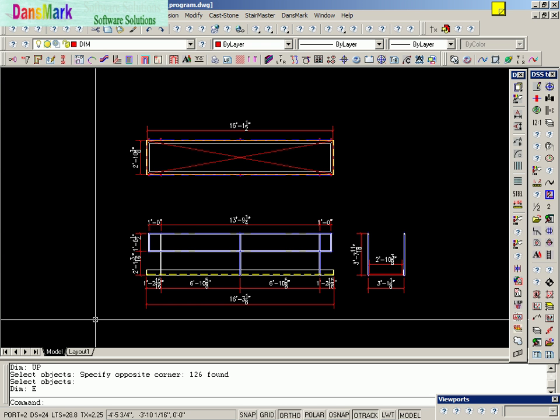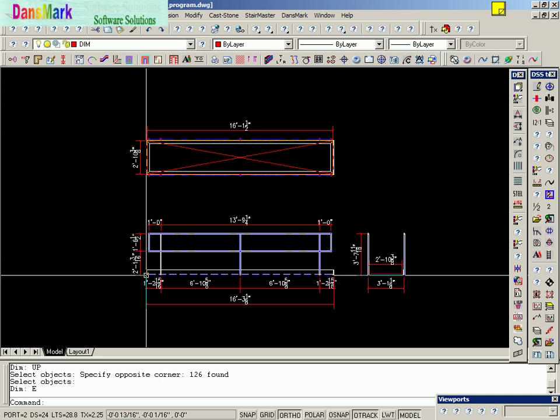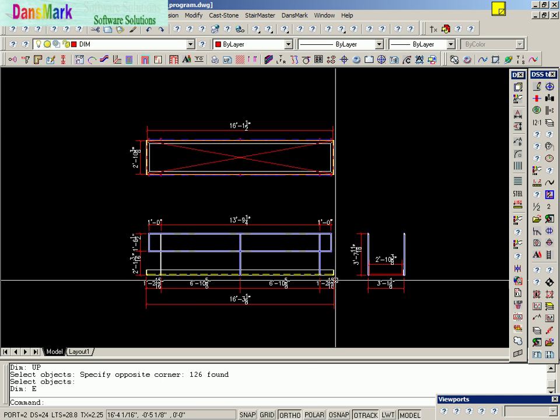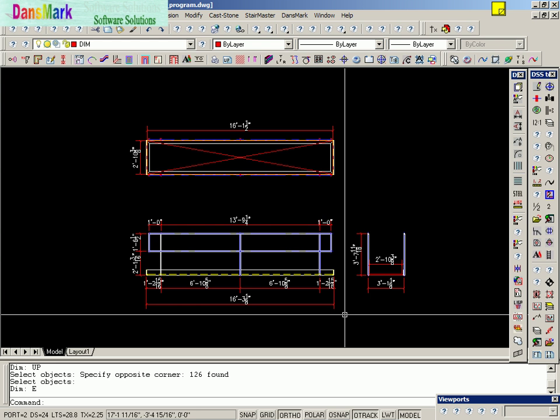In other words, it starts at, let's say, R1 is variable R1, and if you picked a line, the bottom line of this angle from this point to this point, not only would it create the code to command to create that line, but it also would create the variable X1 to tell you how far in the X direction that you went, Y1 to tell you how far in the Y direction that you went, and Z1 that would tell you what direction in the Z plane that you went. So basically you could create 3D programming if you had 3D drawings with this particular code.